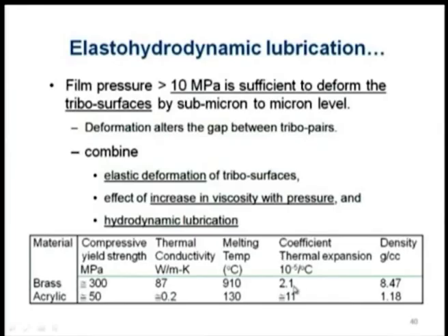There are some factors too: the melting point of acrylic is lower than 130, which means we should not apply or induce too high an ambient temperature. Another reason to avoid high temperature application is the low thermal conductivity of acrylic. Now, we did experiments by making a brass bearing and an acrylic bearing on one test setup, which we can name a journal bearing test setup.